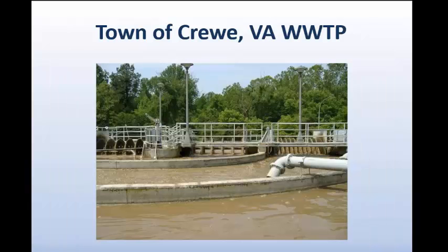Our issue to begin with was, this is a look at our oxidation ditch. Our treatment process consists of 3 concentric channels. The waste stream being treated works its way through each one of the 3 channels. At the onset of our project, all 3 of these channels provided basically the same environment, the same habitat. They were all high in free dissolved oxygen.